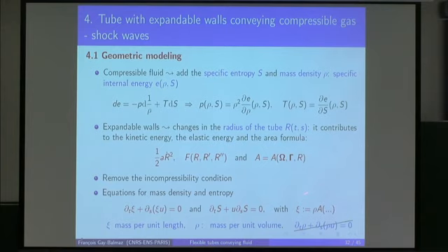So for sure we will have two conservation laws. We have the entropy equation, because we don't have any irreversible process yet. And here we have mass conservation for psi. Psi is not rho. This is the main difference here. There are two mass densities: the mass per unit volume, rho, the one that is used in the internal energy, and the mass per unit length, the one that is preserved by the 1D motion. 1D motion preserves mass per unit length, not volume.